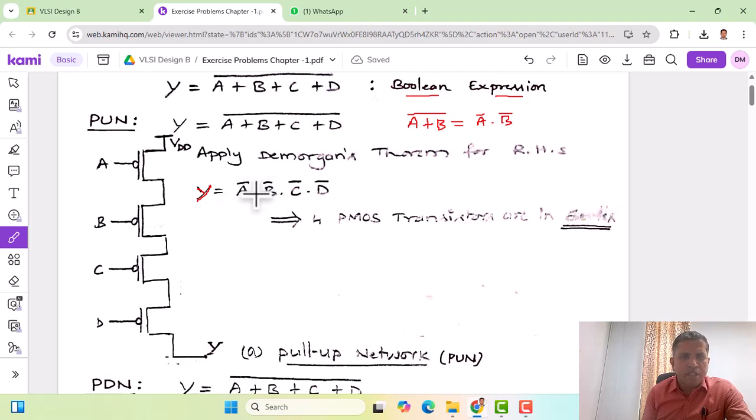As we can see, let us check whether the Boolean expression has met the required criteria or not. Here each variable is in complement form. That's again very good. And on the left hand side, the output variable is in the normal form. And the dots here show that the transistors are connected in series. Totally 4 transistors. Each variable is taken as one transistor.